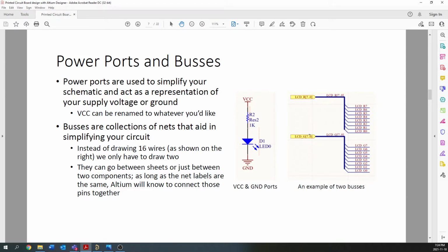If I had another component on this left side here, and I wanted to bring this bus from, let's say, one component here, another one here, I could very easily bring this bus down here and split it up again into these lines to the other components, and very easily reassign which net went to which pin on each one, just moving around the net names instead of redrawing the wires. But again, we're not covering that.